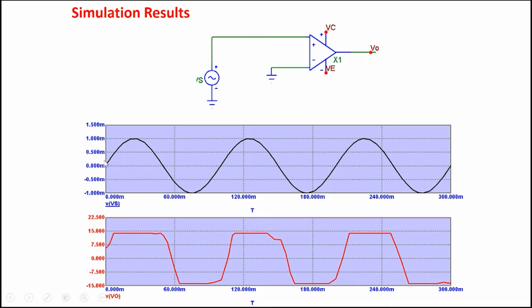And note how much voltage do we require? This is 1 millivolt. If I have something like 0.1 millivolt, that will give us maybe around 10 or so. So very quickly it saturates, and therefore our amplifier is not working properly. This is saturated here, this is saturated here. One of the conditions for an amplifier to work properly is that the output should look like the input. And the output doesn't look like it, it's totally distorted.